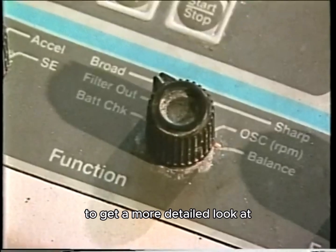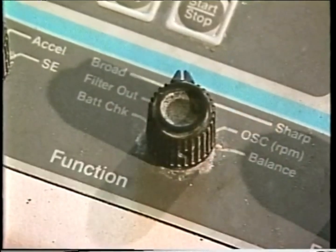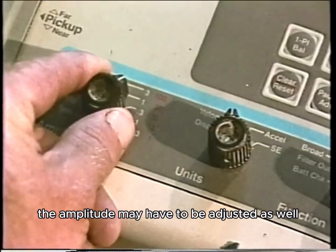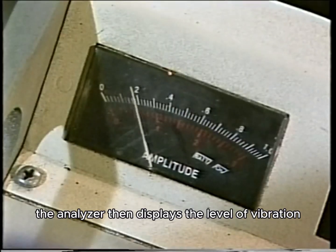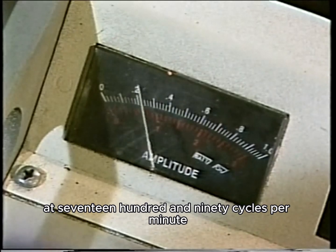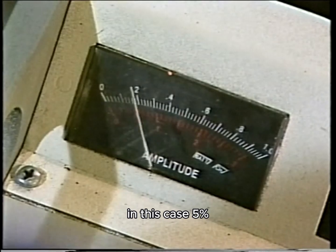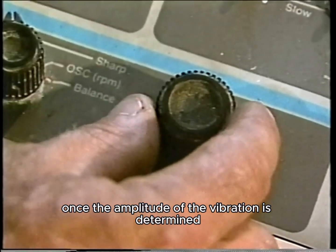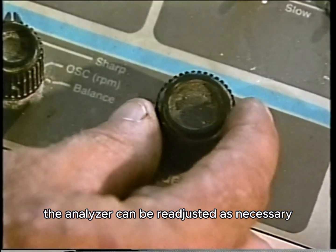To get a more detailed look at that particular vibration, a narrower bandwidth can be chosen. The amplitude may have to be adjusted as well. Then, another measurement can be taken. The analyzer then displays the level of vibration at 1,790 cycles per minute, plus or minus a certain percentage, in this case, 5%.